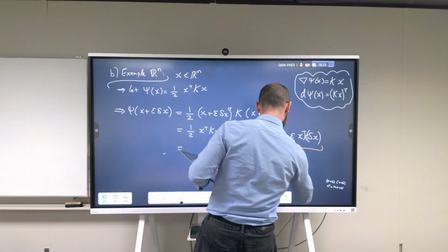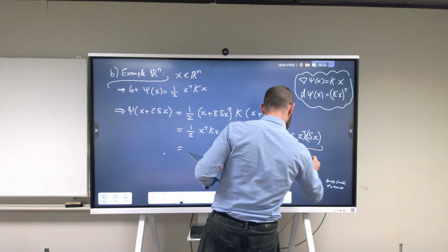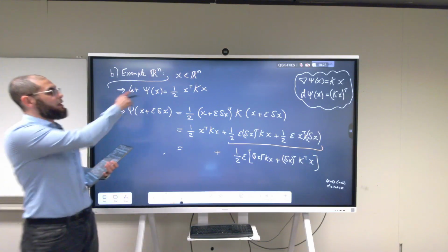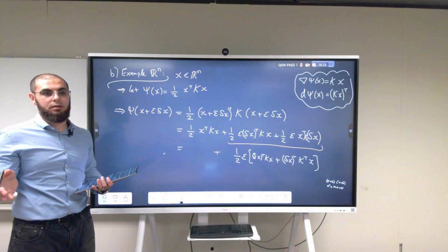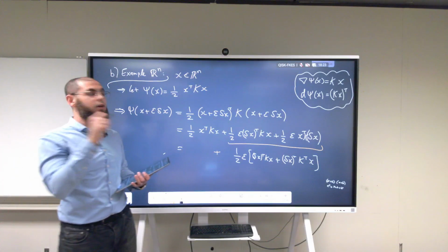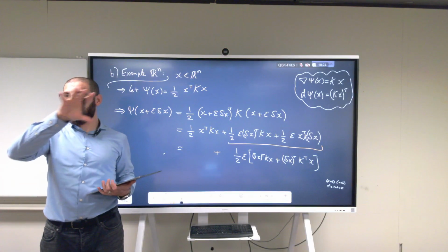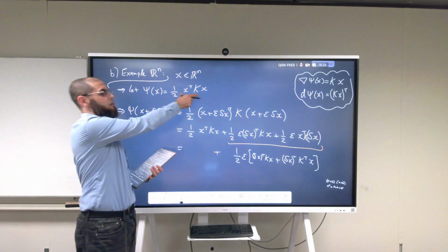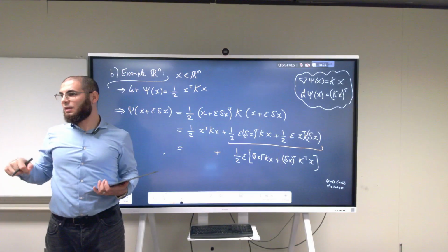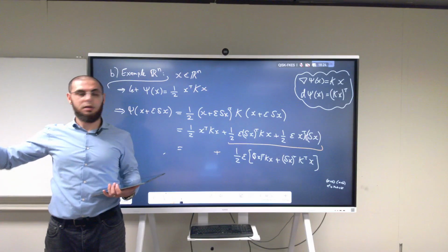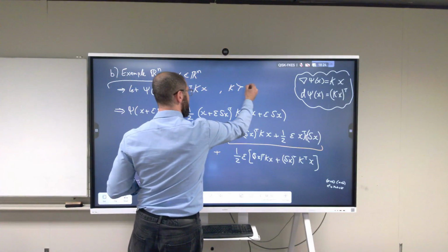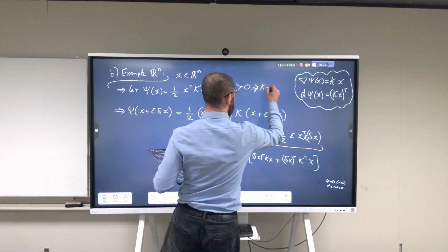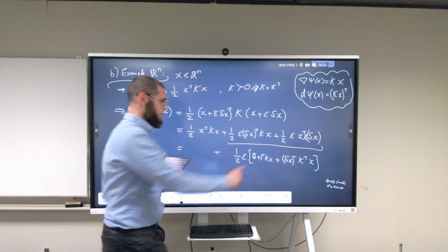It will become delta x transpose multiplied by k transpose multiplied by x. The assumption we're making here is that for this to be positive definite, k has to be symmetric. You remember the slides where we had positive definite matrices. We said we can talk about positive definite matrices that make up positive definite functions only if they are symmetric. Remember that term? And we said if it was skew symmetric, it would actually disappear. So here, k has to be symmetric. It has to be positive definite, which implies that K is equal to K transpose. And thus all of this term is actually